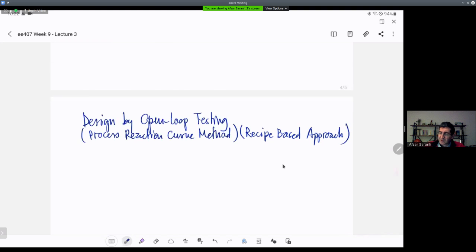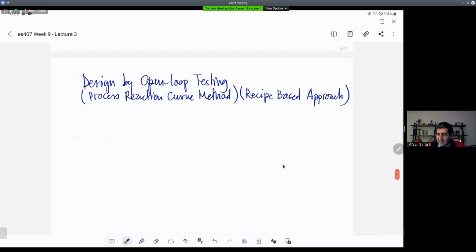Okay? So what's the procedure? You basically manually achieve steady state. That means you put the system in the operating point. So you do this around the operating point clearly in case the system is nonlinear. So you derive the model in the neighborhood of the operating point.